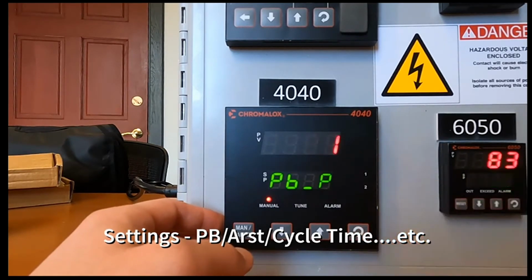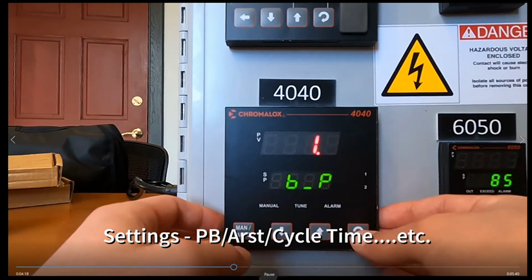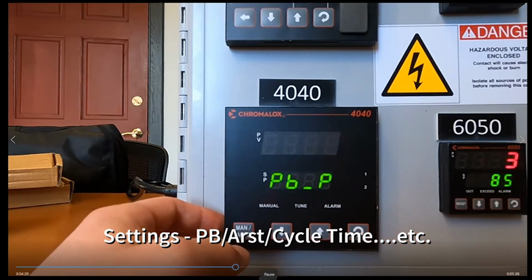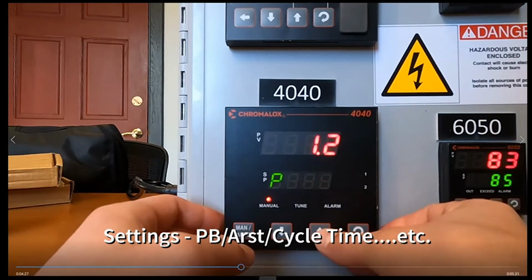Yep. So these are the proportional bands. This is the span I was talking about, going back to the scale range, upper and lower limit of 1,000 and 0. If you're working with a controller that's accepting a thermocouple or RTD input, something like that, this is how you mess with the proportional band of the PID control. This is a percentage, and it's a percentage of that span.